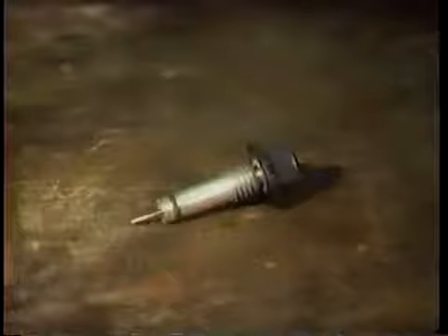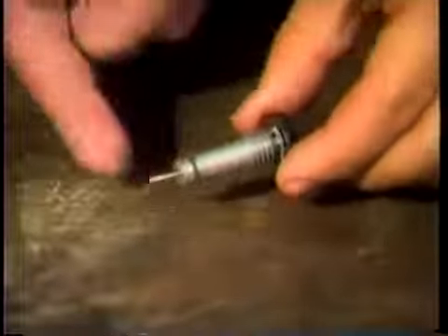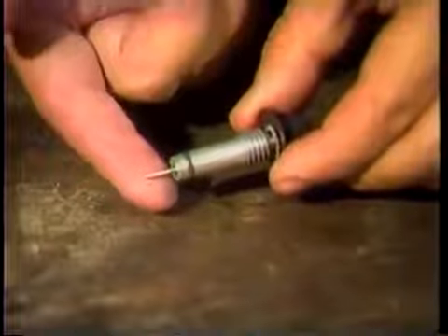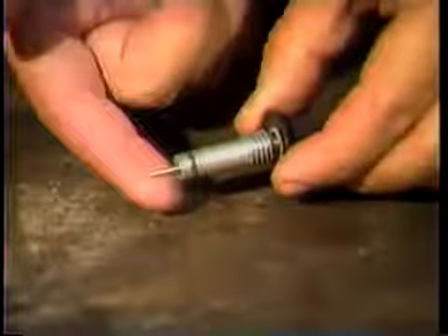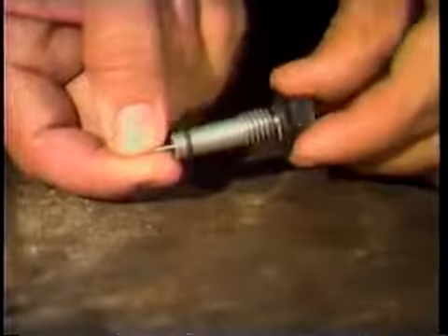The plug-type disc has a wide seating surface. Now, this kind of globe valve enables excellent throttling characteristics for flow control. It can be used under all pressure and temperature conditions. This needle valve is a variation of a globe valve with a plug disc. Now, the plug goes well down into the opening formed by the seat. This gives the valve extremely good throttling ability.